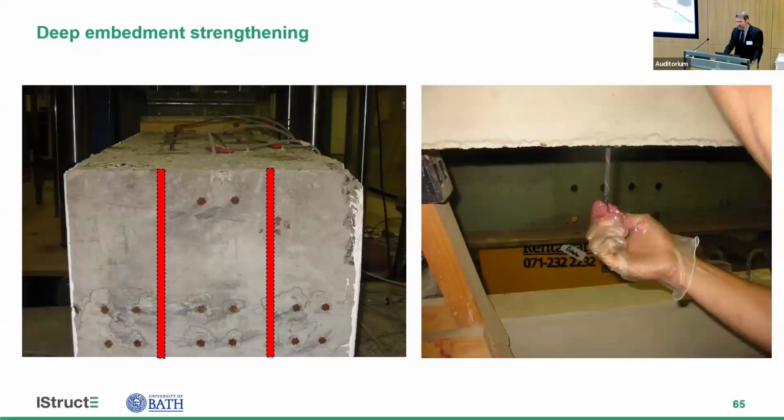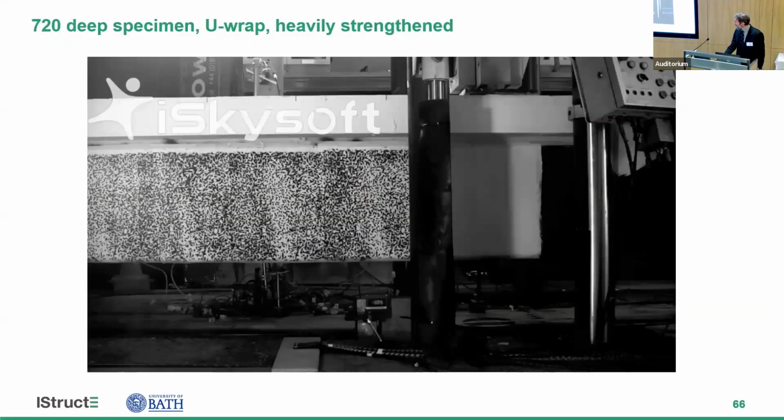And that involves drilling holes right through the section, injecting adhesive into those holes and pushing a reinforcing bar, so in this case carbon fiber bars, but it could be a steel bar, into those slots and bonding them in. So they're inside the concrete.